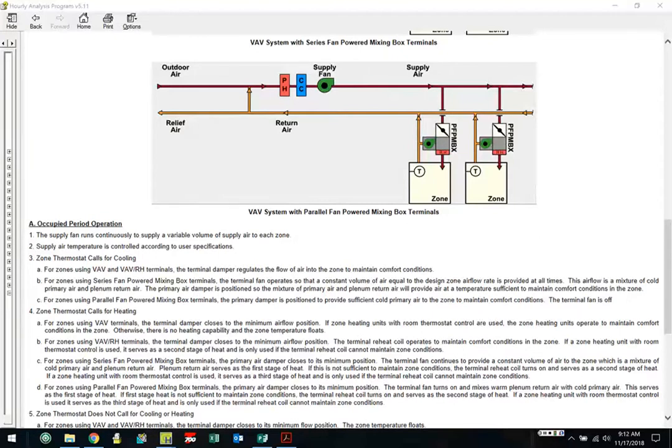So we'll have either, in the wintertime, we'll use the economizer for free cooling. In other words, we'll bring in outside air to cool the building. By the way, when we do that, that's really healthy for the building. It's expensive because we have to treat that cold air, warm it up a little bit. But when we're using outside air for cooling, we're really ventilating the building, so it works out really well. We typically have fewer issues with building stuffiness in the wintertime than in the summertime. So the free cooling is going to go on. We're going to be moving those dampers in order to maintain a 55 degree or 57 degree discharge.